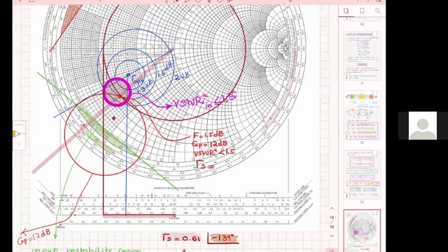It's not quite accurate, but somewhere there, which means that if I were to get my G maximum like 14.7, I would need to have much higher noise than 2 dBs. So I'm trying to find the highest possible, because I cannot go further in. If I go for a bigger red circle than the one I have for 12 dBs, then practically I will go to lower noise, but I will have lower gain. Is that clear?